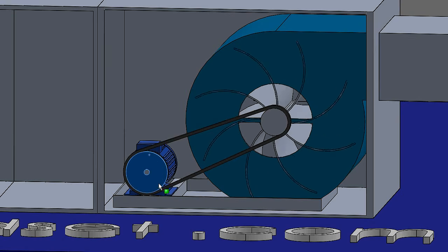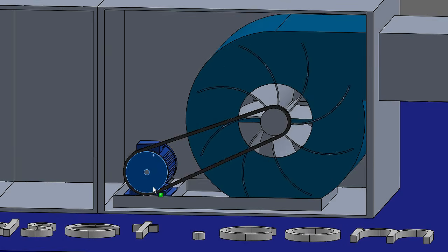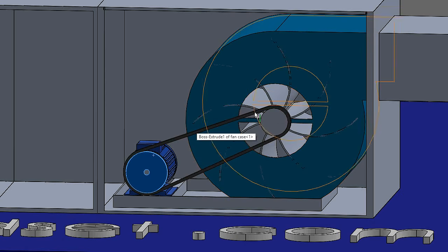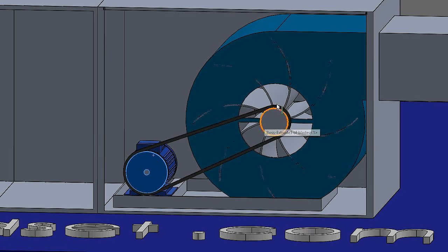So as that spins, and it goes faster and faster and faster, that draws that air. All that air is traveling along the duct there, and it's being sucked into these sides here, on the back and the front as well. So as that induction motor there and the pulley spins, it pulls all the air in, and that starts to fill this void. The back of this one is obviously pushing that air. It's coming around, and as it's doing that, it's kind of being flung off the side here. You imagine like a centrifugal force. If you spin something, it wants to go out.